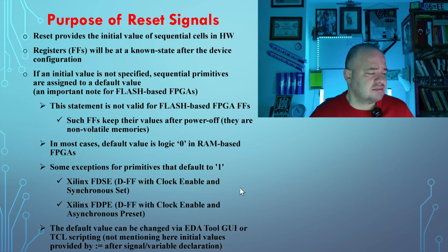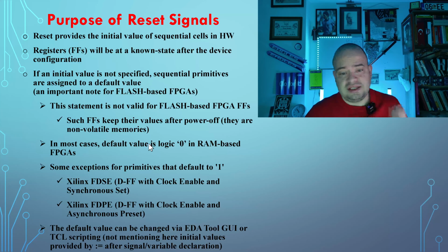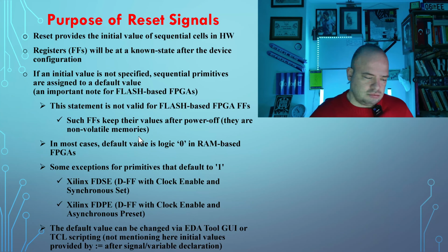You can add some logic analyzers and see that they are keeping their values unless you use an appropriate reset architecture. Of course, you need to write the HDL code and provide those reset statements. Also, you need to have external resets incoming after the power cycle, resetting your flip-flops properly. You also need that.